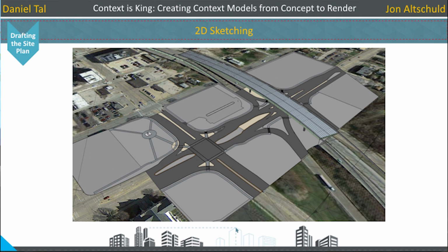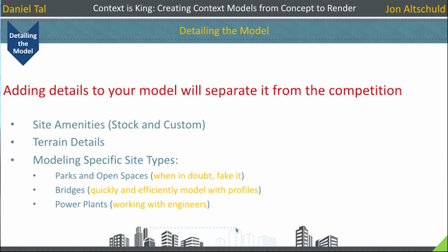And that's that. So then once you have the site plan drafted and integrated in the terrain, we're in SketchUp. Go to 3D. So we're going to start just popping up your buildings. You might have building models that you already have from the architect. You can locate them right onto the site plan. But it's adding all the detail.